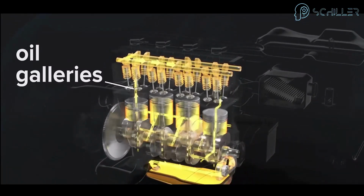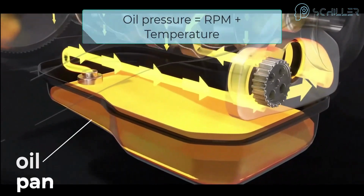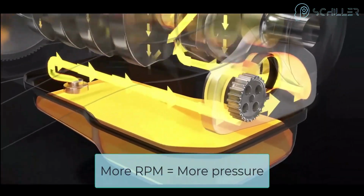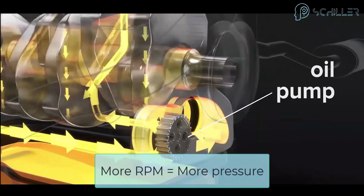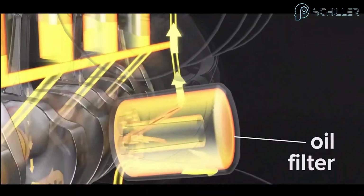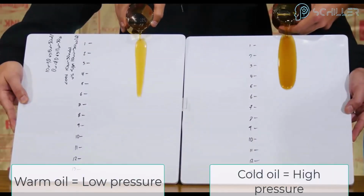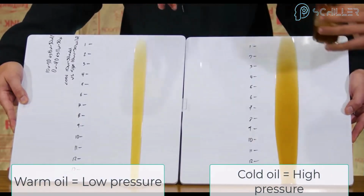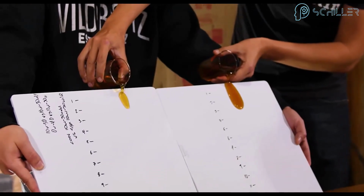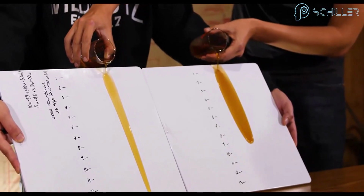Oil pressure is mainly influenced by two factors: engine speed and oil temperature. As RPM rises, the oil pump spins faster, increasing flow and pressure, right up to the point where the relief valve opens and holds it steady. Temperature plays an equally important role. Cold oil is thicker, so pressure is naturally higher, while hot oil thins out, reducing pressure. This is why, in hot idle conditions, worn engines sometimes trigger the oil pressure warning light.